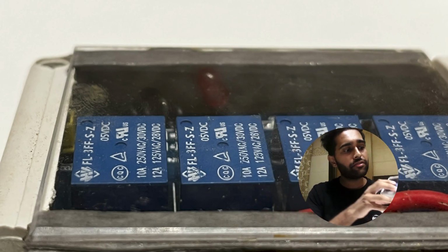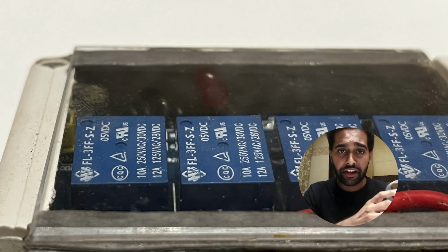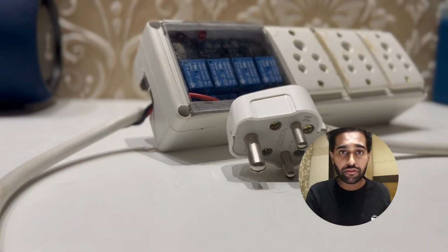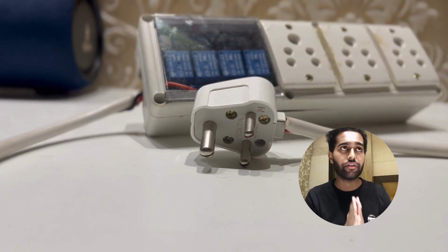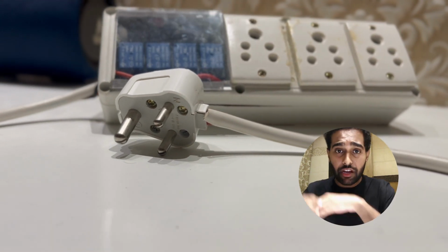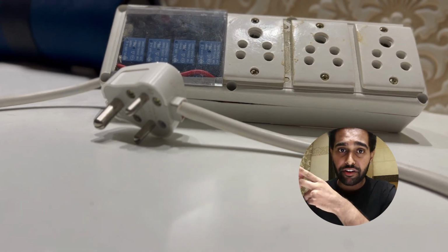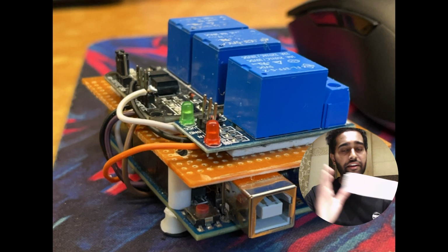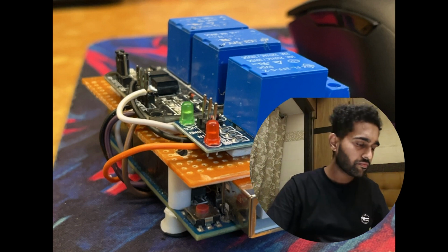When the relay gets a 5 volts input from Arduino, it switches it to 220 volts AC to the device so that the device gets turned on. As you can see, we have also integrated an LED unit, so the user can know when to show the gesture to the webcam and trigger the socket. Now we have one relay and one Arduino, so we stacked them on top of each other to get a compact size for our prototype 1.